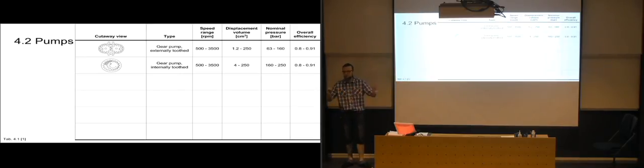So you have much more contact between your two materials here, which means that you can handle a much greater load than what you do here, where if you get too much pressure in here, your teeth will break off, basically, because it's just one tooth on another tooth. And here you have several, so that you have more contact, and it can handle more strain.